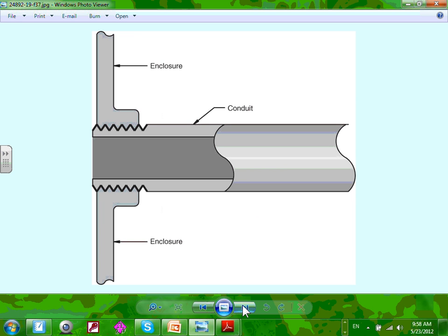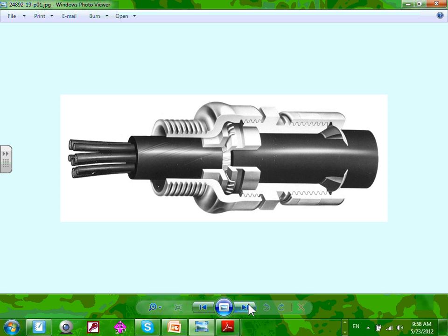What they do, you have to have, I think, 4 threads when you thread these, guys, because when you have an explosion proof, the gas will seep through the threads, and as it seeps through the threads, Chris, it will cool down. That's why they use the threaded. Say you have an explosion, now that gas has to go somewhere. There's a big expansion, thermal effect, right? So that will seep right through all these threads. And by the time it goes up and down, up and down, all the way, it will cool down. So that's why we use threaded in explosion-proof locations. Same thing with the cables.